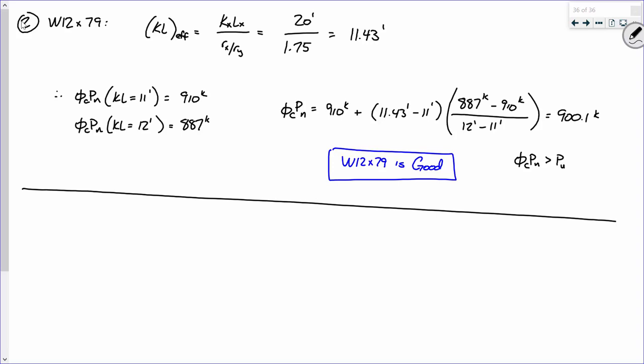Because the equations are very, very nonlinear, sometimes you can have a column that has a low efficiency, but it's still the most economical selection. And how do you know it's the most economical selection? Because we're literally cycling through every single column in the manual. So the measure of efficiency really isn't a big deal. All right. Should we press on?